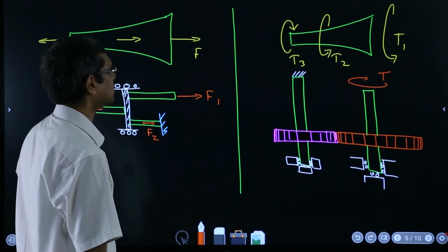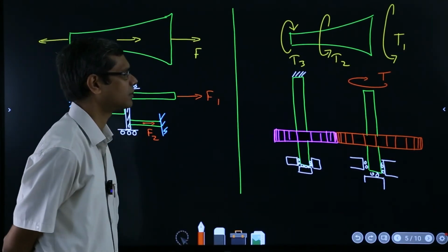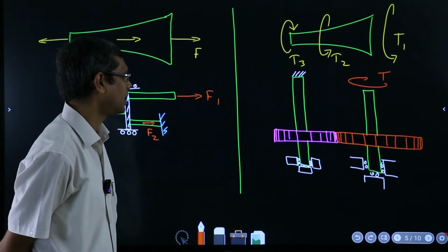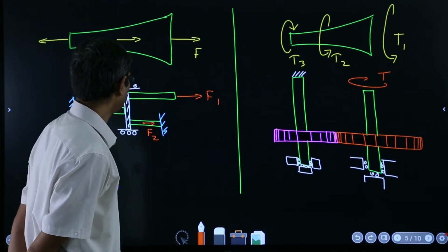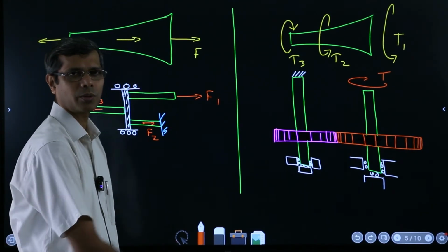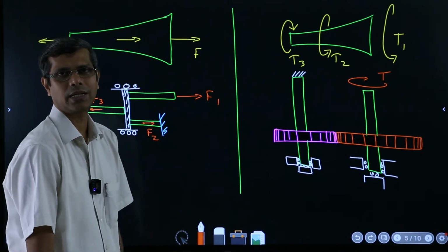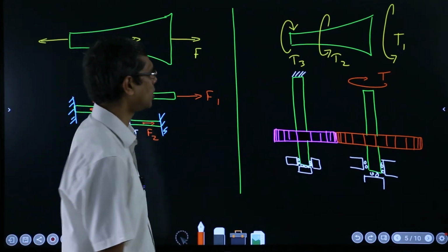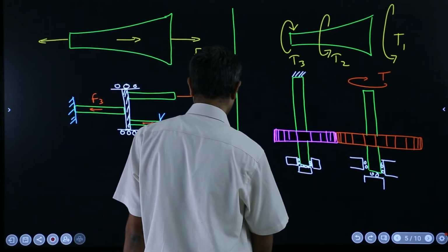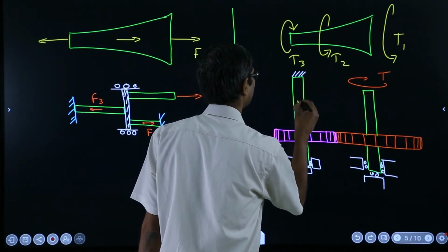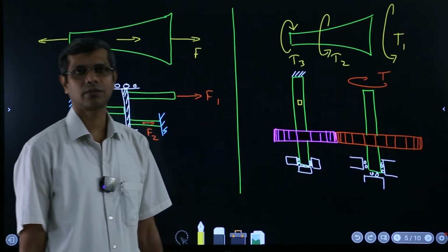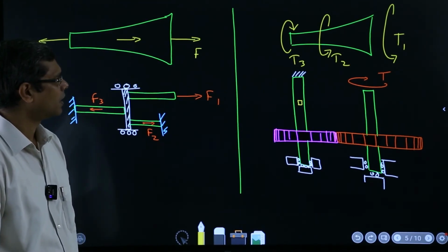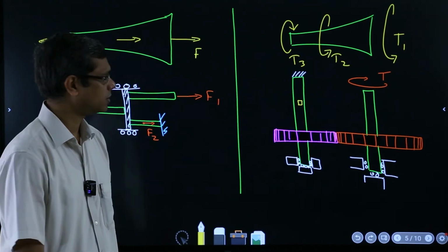So in such cases, how to get the deflection, total deflection, then maybe stresses in the shafts, in the gears or whatever. So problems can be, I am just talking about the configuration, then after that the problem can ask many things based on that. In fact, a Mohr circle problem can come from here if you consider an element here maybe, and the state of stress of that particular element could be asked for a discussion using the Mohr circle.